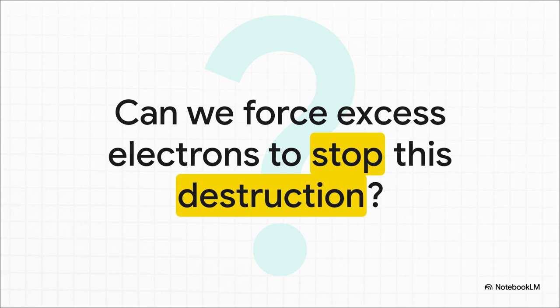Engineers use this exact science for a genius technique called cathodic protection. They literally pump direct current into pipelines and bridges to turn the entire structure into a protected cathode, basically halting the anode's decay right in its tracks. And honestly, that is the incredible power of truly understanding the electrochemical mechanism of corrosion. I really hope this explainer has sparked your curiosity to see the hidden electrical circuits operating all around us.